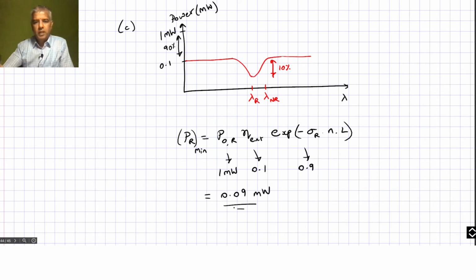By the way, we are talking about picking up 90 microwatts of power, and we are saying the responsivity needs to be only in the order of 1 amp per watt. So that already tells you that you don't need an APD photodiode, because you have so much power already. So you can go for a PIN photodiode. But then mind you, the wavelength that we are using is 1100 nanometers. So what material would you use to pick up 1100 nanometers?